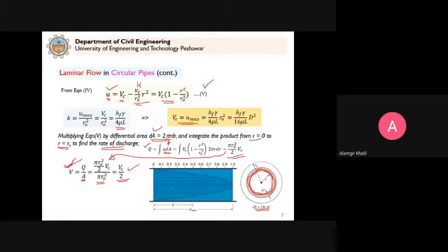And this is what you can see here, shown in this diagram. So this average velocity here is half of the center line velocity. And this is also true in mathematics, where they say that the mean height of a paraboloid is 1/2 of the maximum height.